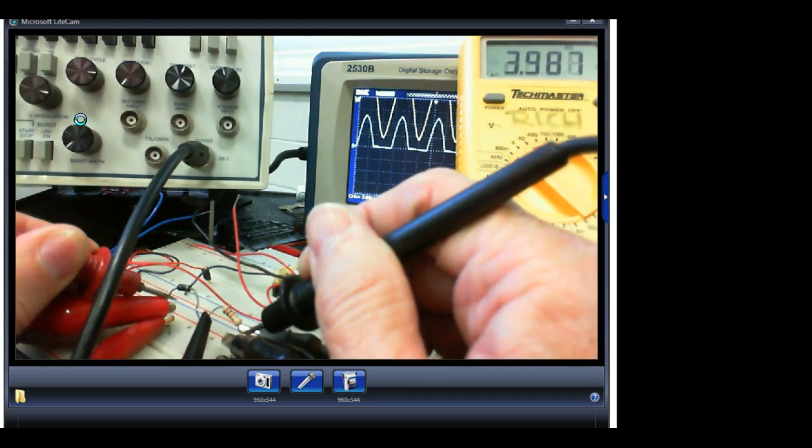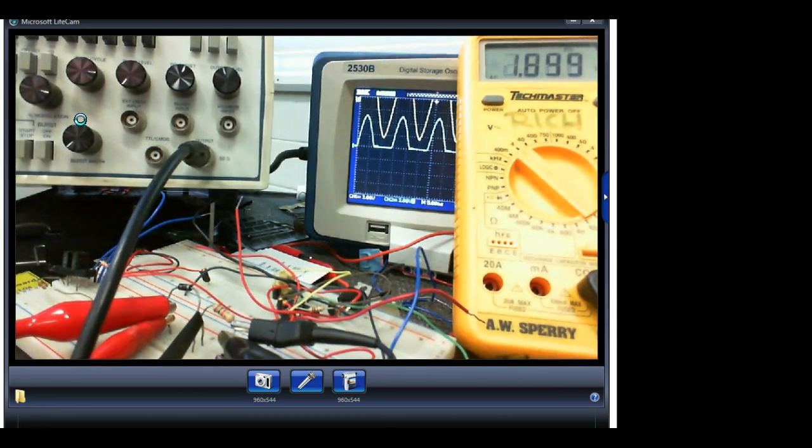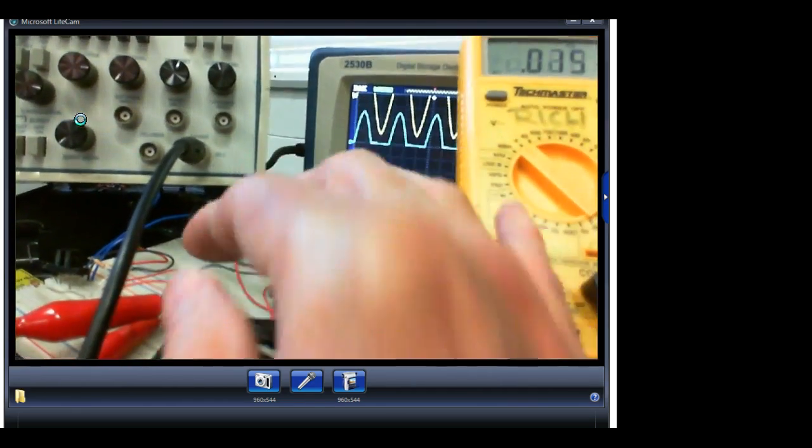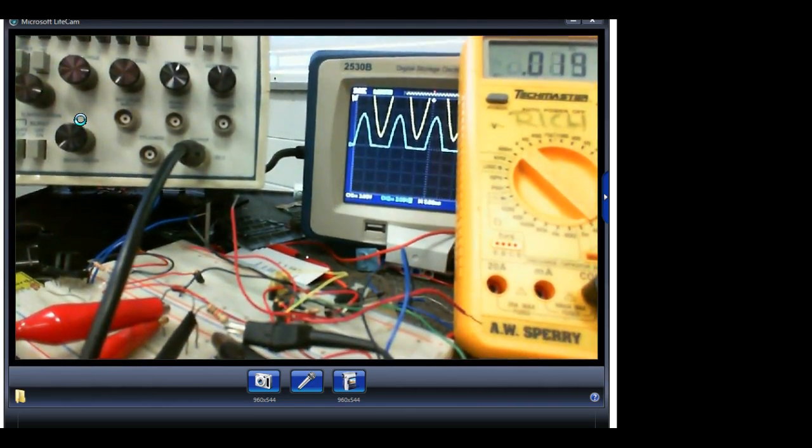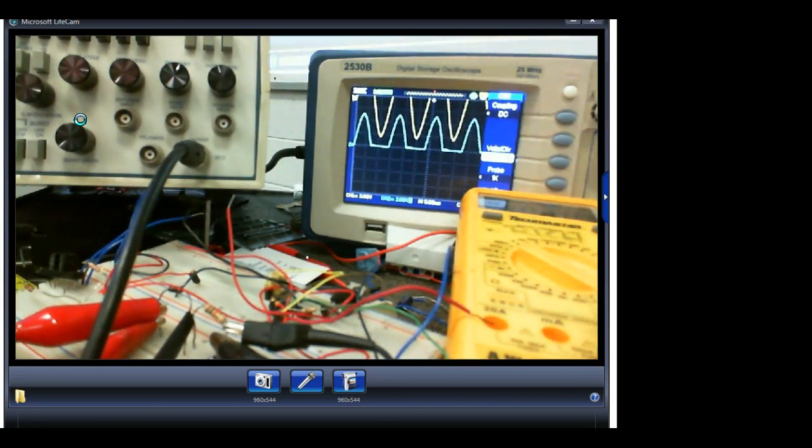But that's RMS. So if I wanted to see V peak, I would do what? RMS divided by 0.707. What do you come up with? Hopefully it should come up to be 6, or close to it. No, I'm measuring across the actual source. Should be about 6, right? You understand? 0.707 is just a rounded number. It's actually... no, not sine of 45.